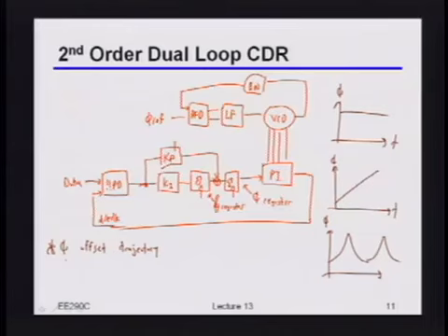So if you have a spread spectrum design, you'd want something that would not only figure out what the frequency offset is and what the nominal phase offset is, but in fact what the spreading frequency is, what the spreading rate is, and so on and so forth. Okay? There's not too many systems that you will deal with that have to deal with that. But it's again something important to know about, because it gets to this general principle of designing your CDR loop so that it indeed tracks whatever the trajectory of your input is doing. Okay?